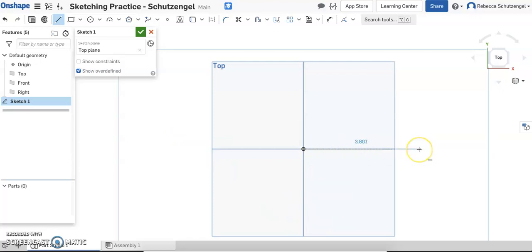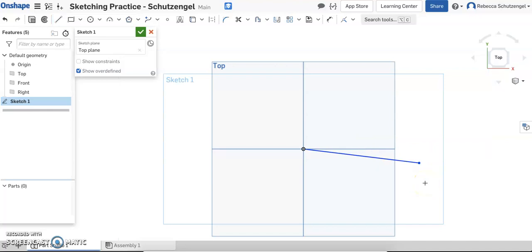and then I'm going to draw it horizontal, right? And notice how before I even click to put the line down, there's that little pop-up just below my cursor with a horizontal line showing that it's actually putting a horizontal constraint on the line automatically, and I don't even have to do anything else. Of course, I can move the line so it's not horizontal and it won't have that constraint. So I'm just going to draw that one line and escape it.